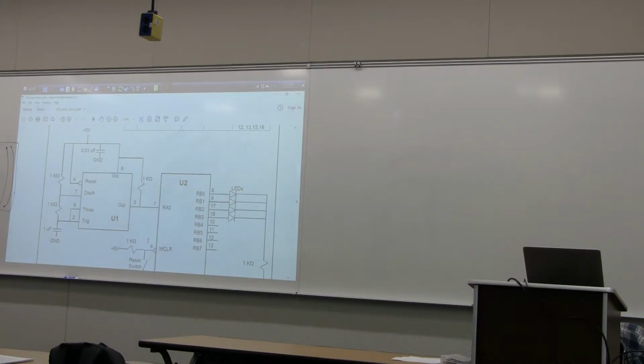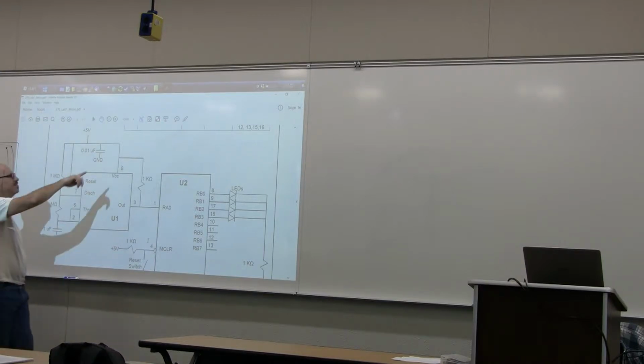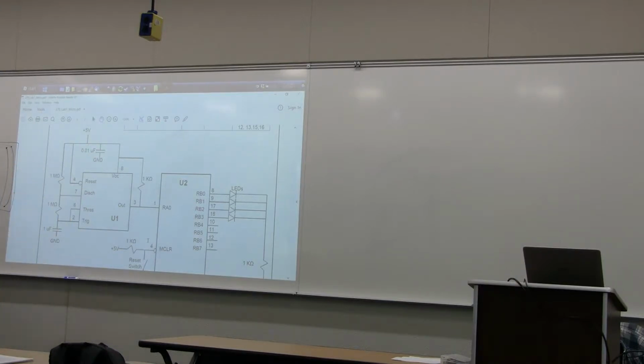I don't need long wires and so on. All right, so how do we wire this? Well, pin 1, it's off the screen, but pin 1 has to go to ground. So take this and just run a jumper to your ground line. Pin 1 is done. Pin 2 needs to connect to pin 6. So go into this line of holes and just run a wire over to pin 6. Pop it across the top of the chip. That takes care of this.